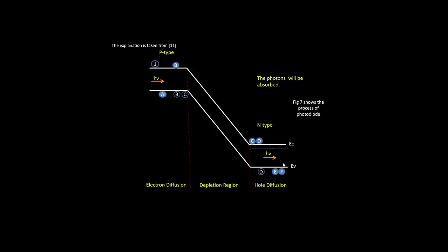Photogenerated electron-hole pairs near the depletion region have a chance of entering the depletion layer by random diffusion, and therefore contribute a charge to the external circuit. Electrons and holes generated away from the depletion region wander randomly until they are annihilated by recombination.